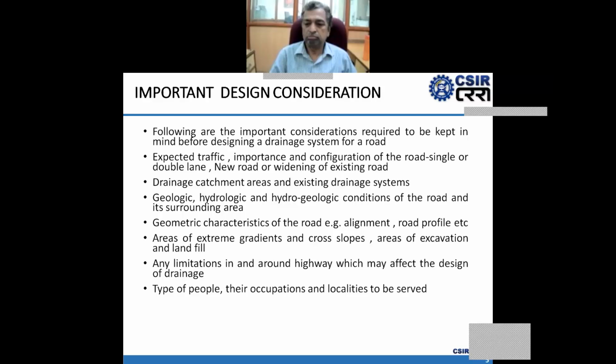For the design of a drainage system, before designing it, we have to keep all these parameters in mind. What is the expected traffic, and the importance and configuration of the road: a single lane or double lane road, a new road, or a widening of existing roads.